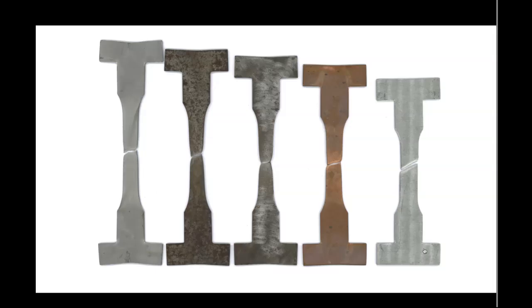By the way, stainless steel will have some carbon, generally less than 0.5%. So it's almost like those steels, which are second and the one in the middle, but with nickel or chromium added to that. But the stainless steel that we had was not necessarily lower quality. It's 304, just one of the run-of-the-mill types of stainless steel, which is used as a construction type material.